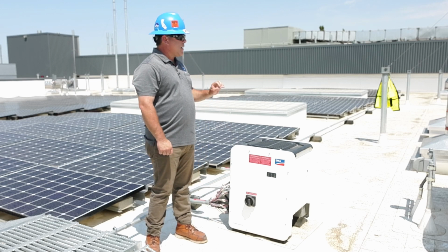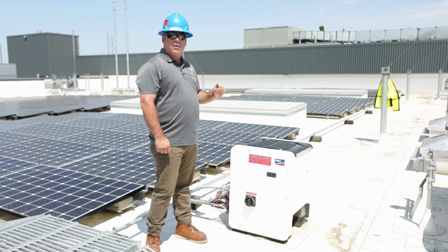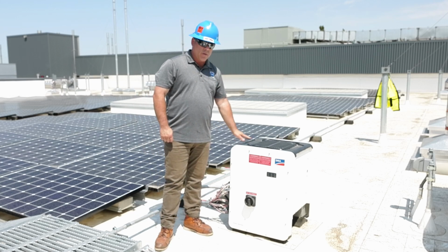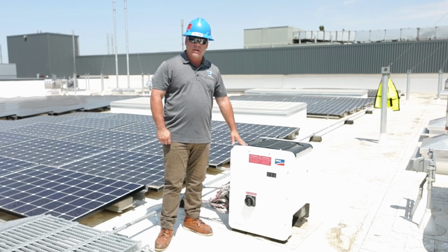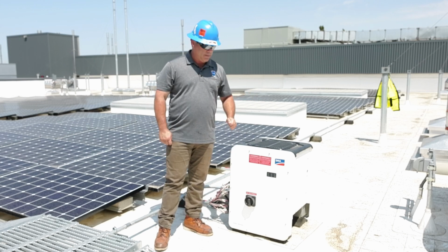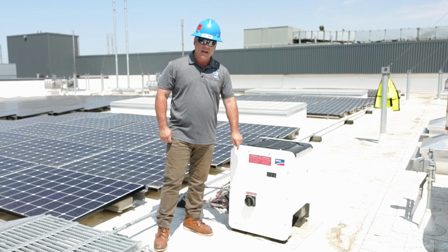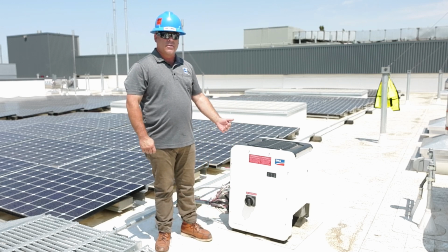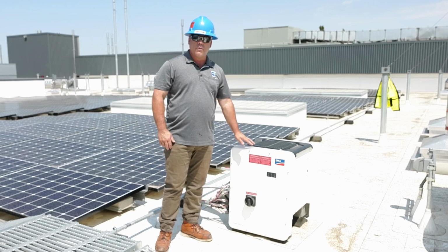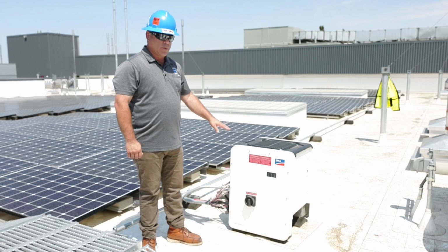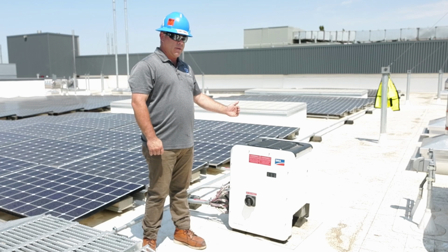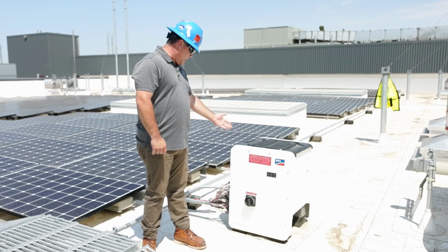If we want to test one, we would open up the breaker at the distribution board. AC power will not be going into the inverter. The inverter will see loss of power, will turn off. We can open up the AC side, DC side, turn it back on, and they should restart the minute we provide power from utility. Any troubleshooting has to be done with a tablet. So we would have to connect, again, Bluetooth, and determine what fault it is and follow that path. Everything else, it should be physical.